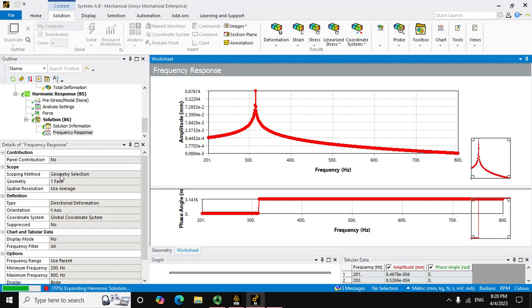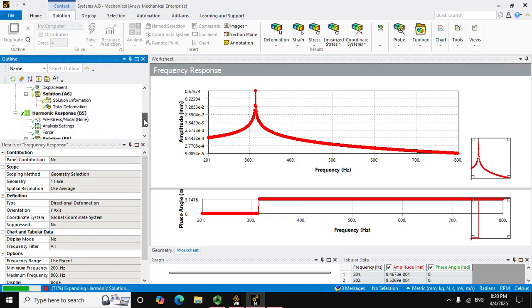See what happens. The smaller damping is gonna increase this peak here, and in theory if you have zero damping, that's gonna be infinite. Should have infinity here around the natural frequency. So let's see what we get. If you like, you can later make a similar model and then play with that.